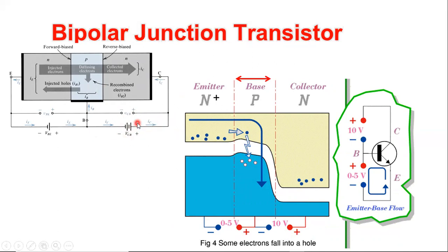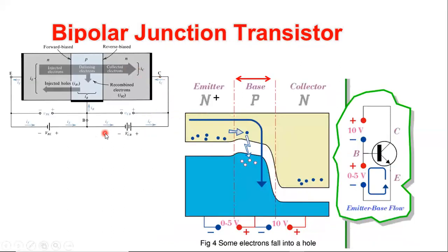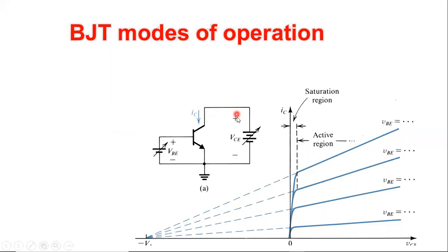That means that this is a reverse biased junction, because now you have 5 volts here and 0.7 volt here, so the positive voltage is connected to the collector. The collector is an N-type, that's why this junction is reversed. So as long as you put 5 volts here, you have a reverse-biased collector base junction, and that means that your BJT is working in the forward active mode. Okay, let me now start to decrease the voltage applied to the collector emitter junction.